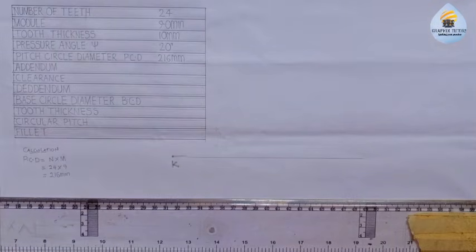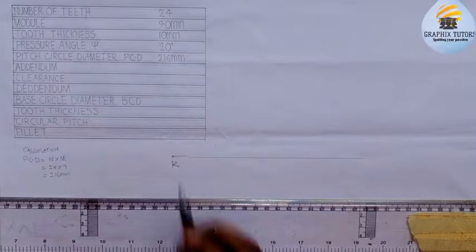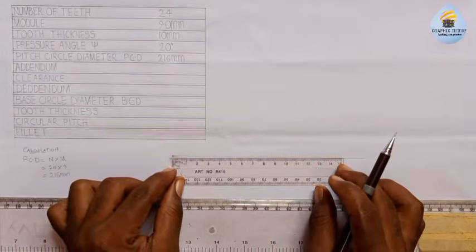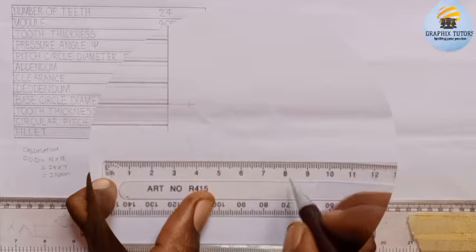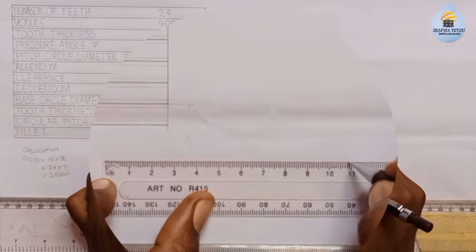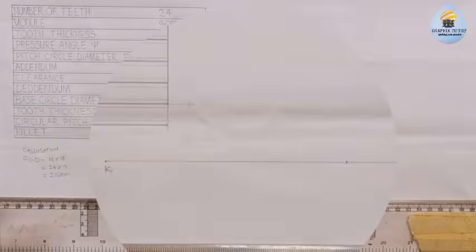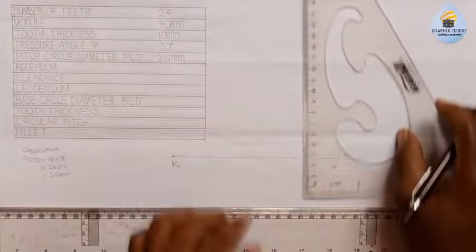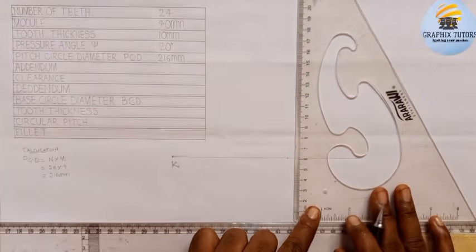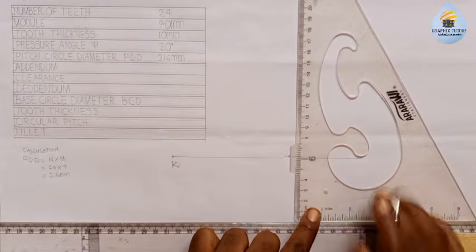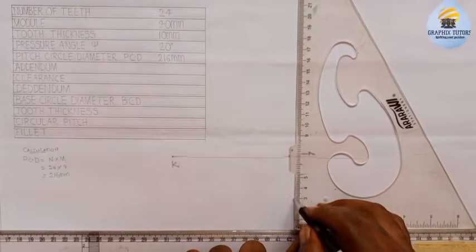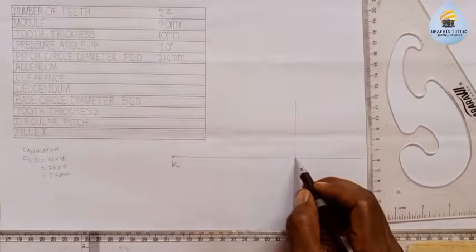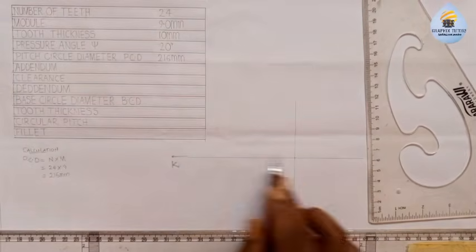So I will now take my meter rule and measure 108 from K, right? So my reference point is K. If I place it this way, from here to here, this is 100, and 108 is here. Is that taken? So at that point, I am going to draw a vertical line this way. I'll draw a vertical line at that point. That will be my reference line also. So this is where I'll take my measurement from. So from here to here is the radius, right?